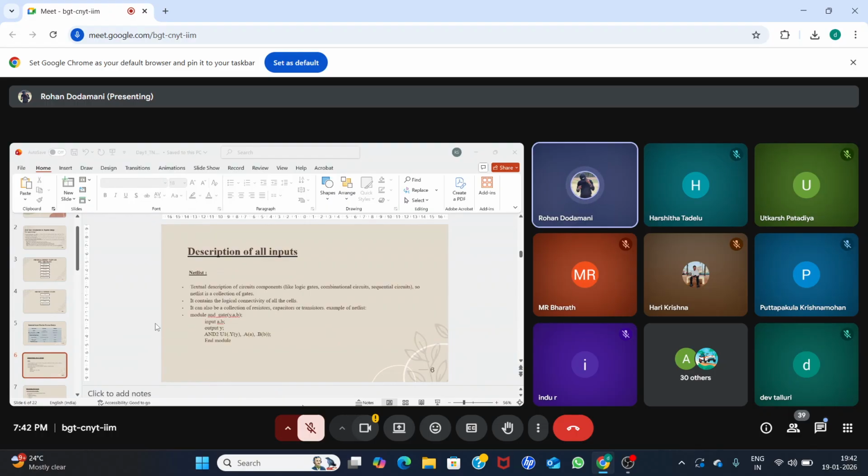It will start with module and end with endmodule, and in between all the data about the gate's inputs and outputs and what functionality it performs will be present. Similarly, each and every cell's information will be present in the netlist file. Apart from this, the netlist file contains some extra information like hierarchical information, module information, and instance information. But the main thing it contains is this type of data.